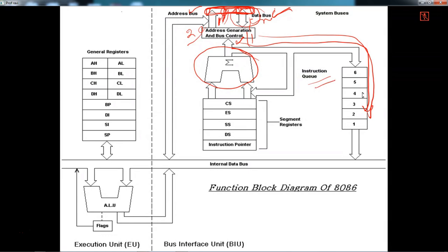The difference between 8085 and 8086, I will give you in detail in the next class, don't worry. But what we have discussed, whether it is there with 8086 or not, now we are seeing. These instructions will be passed to a queue, and each entry can store 8 bits of data, right? So 8 bits each, like that you have a 16-byte queue.